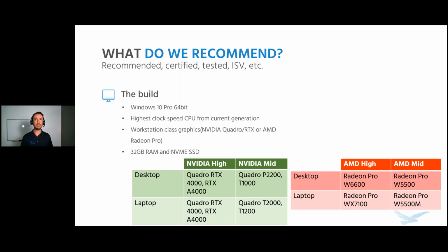So just to talk about the reason for me bringing up workstation versus non-workstation graphics cards. It's not that you would be running an unsupported platform. Let's say, for example, you had a non-workstation class graphics card like an NVIDIA GeForce RTX card. It's just that graphics card was never submitted for testing, nor will it ever be, and it will never be certified by SolidWorks. It'll never show up on their hardware certification site. They only test and certify the workstation class.